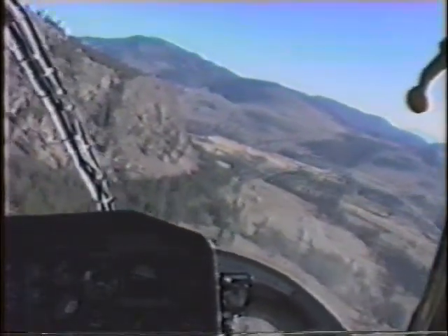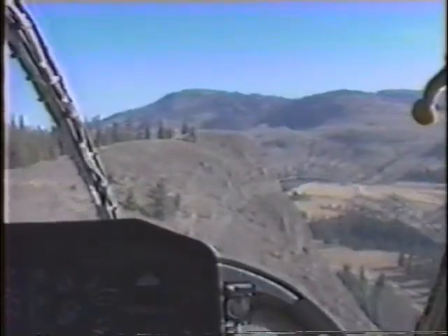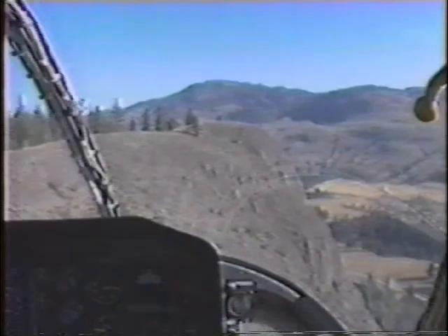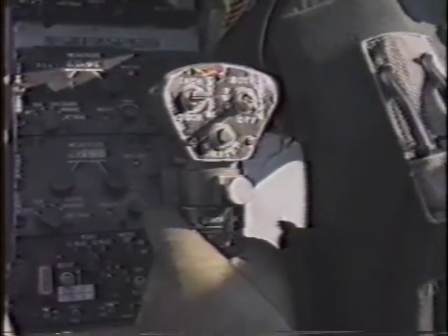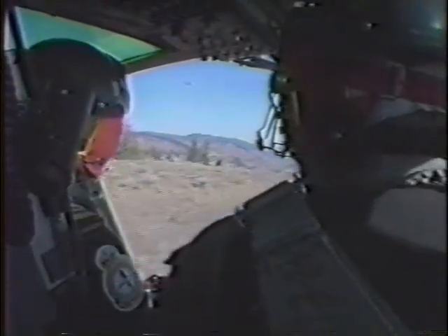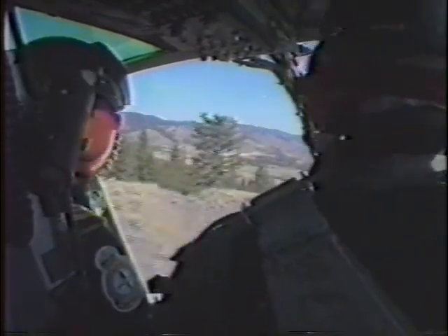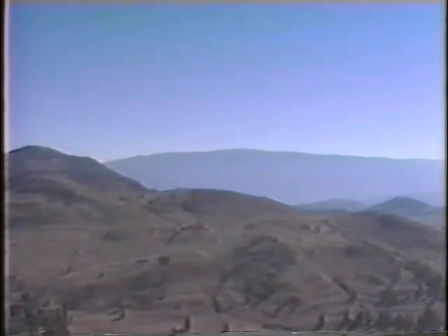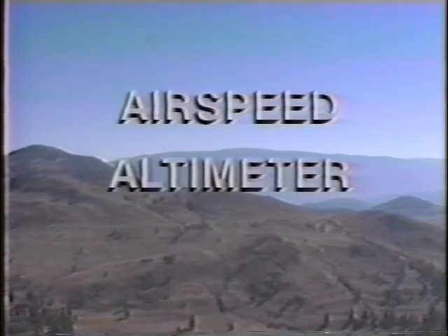During these passes, you're assessing the feel of the various wind factors on your aircraft by paying attention to relative ground speeds, power requirements, and turbulence. And you're looking at the suitability of the LZ. A good recce checklist to constantly be repeating is airspeed, altimeter, outside.